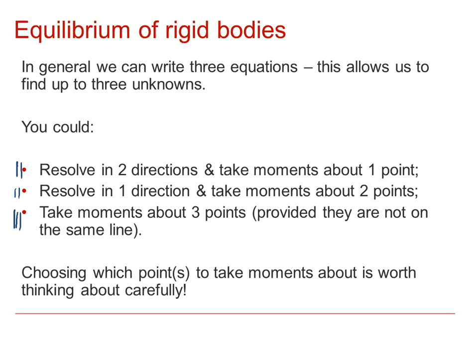The choice of points for taking moments is actually worth considering quite a lot when you're thinking about a problem. The reason for that is if we've got unknown forces at some point, then if we take moments about that point, those forces produce zero moments.